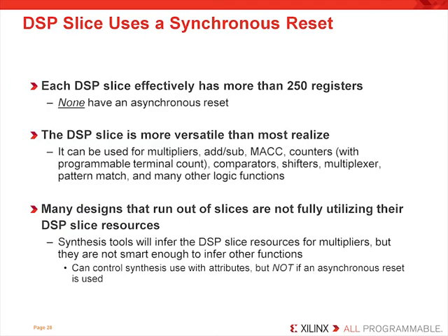It is very important to remember that one of the biggest reasons to use a synchronous reset is that certain dedicated hardware resources simply don't have and don't support an asynchronous reset. For example, to infer the DSP resource will require a synchronous reset to be coded in your HDL. So if the user is going to infer a multiplier, it will have to include a synchronous reset behavior. Unfortunately, synthesis tools cannot infer all possible configurations of the DSP slice, so this will require you in many cases to instantiate the function you want with the core generator.